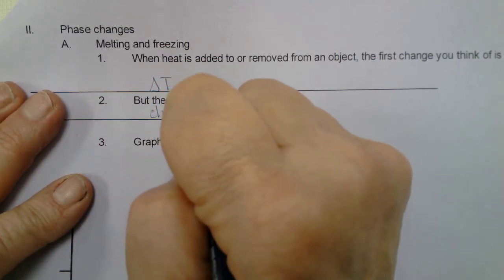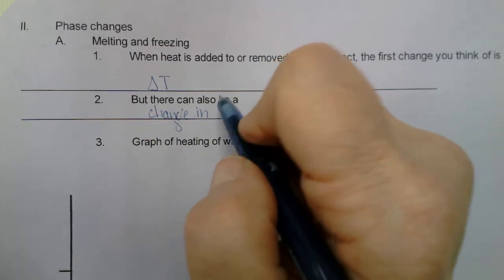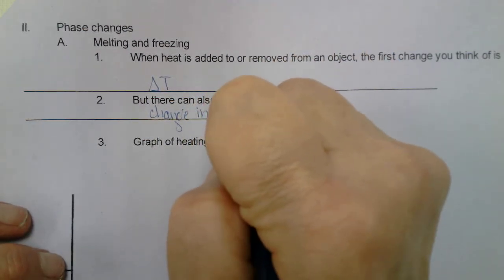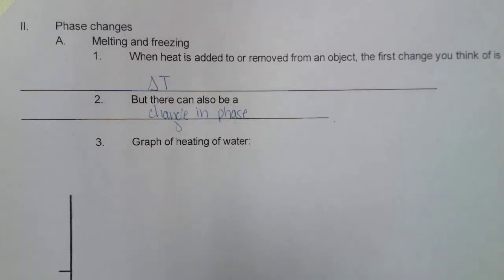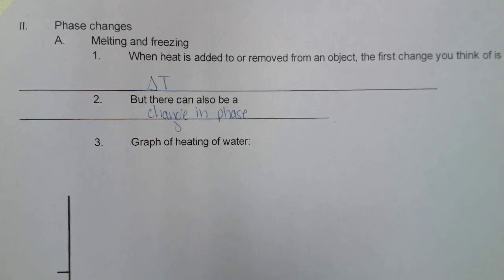And that requires heat for that to happen. And when it is changing phase, it is not changing temperature. Let me say that again. When it is changing phase, all of the heat that I'm pumping into this system is now going into breaking those intermolecular bonds that will allow for a phase change. So the intermolecular bonds that make it a solid have to be torn apart, and that takes energy before it can then start putting that thermal energy into increased kinetic energy of the molecules.